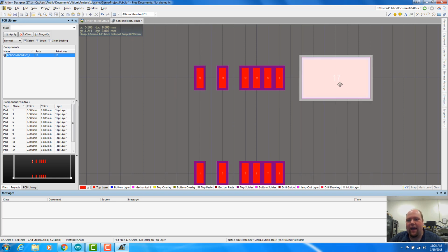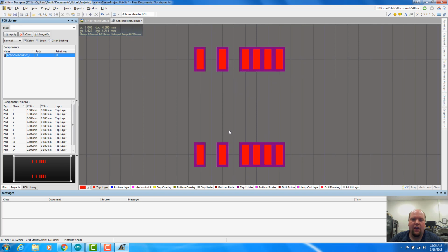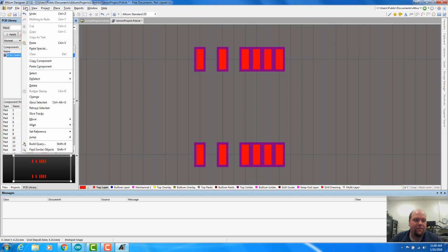And that is I'm going to drop this pad down somewhere. And then I am going to just delete it. I'm going to Control-X it. And Altium wants me to say, before I cut this thing, where the center of motion of this thing should be, so I'm going to just choose it. So what I can do to find the center of this is move the midpoint of our grid. I can move the center point of the grid to the middle of this footprint, and to do that I can go to Move, Set Reference Center.